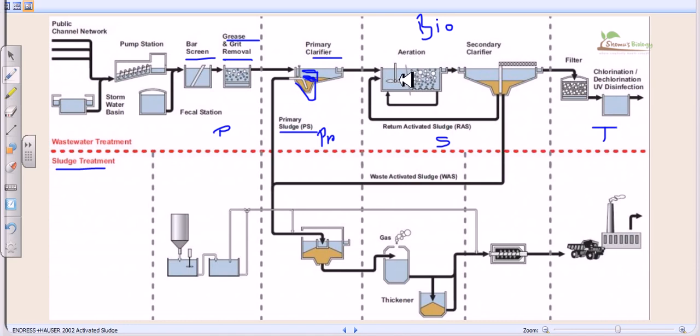We propel a fan here, and we keep adding air bubbles, and it helps the bacteria which we add to this water to grow and multiply very rapidly, and those bacteria love to eat those nutrients stored in this wastewater, because this wastewater consists of human waste, so bacteria can feed on it. So we need to select the type of bacteria that we use in this aeration basin, because those bacteria must be aerobic type, because there is a lot of air in this case.